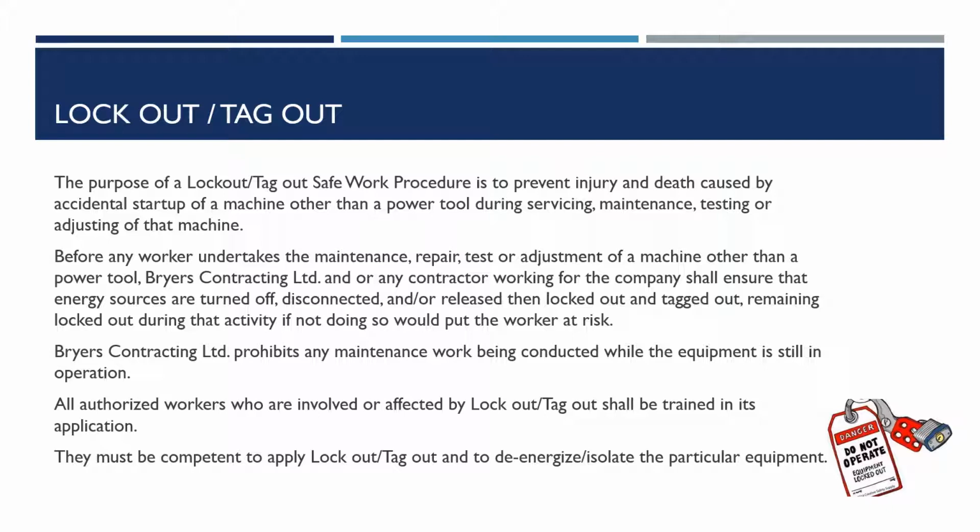Lockout-tagout. The purpose of a lockout-tagout safe work procedure is to prevent injury and death caused by accidental startup of a machine other than a power tool during servicing, maintenance, testing, or adjusting of that machine. Before any worker undertakes the maintenance, repair, test, or adjustment of a machine other than a power tool, Bryers Contracting or any other contractor working for the company shall ensure that energy sources are turned off, disconnected, and/or released, then locked out and tagged out, remaining locked out during that activity. If not, doing so would put the worker at risk.